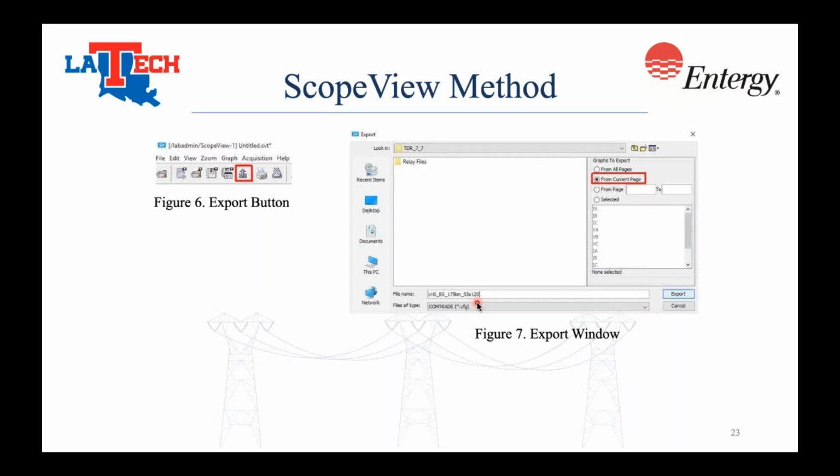The export feature generates 1999 standard Comtrade format, but that's okay for this application. Many possible file types can be generated here, but be sure to select the Comtrade for this purpose. However, the .text and .map files can be very useful for different testing applications.